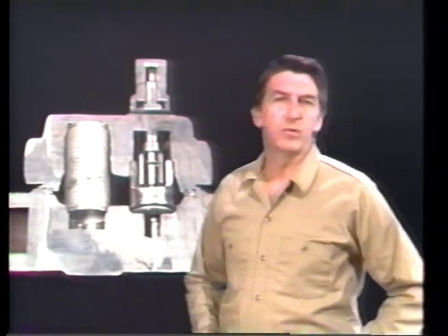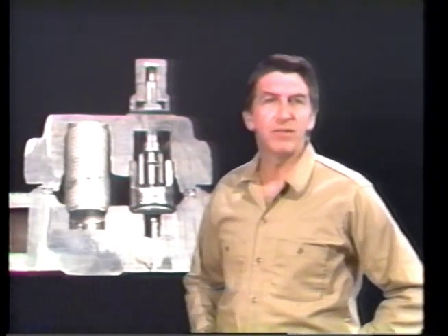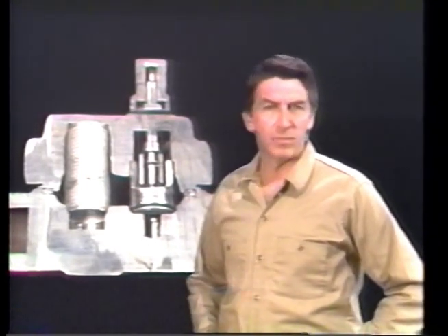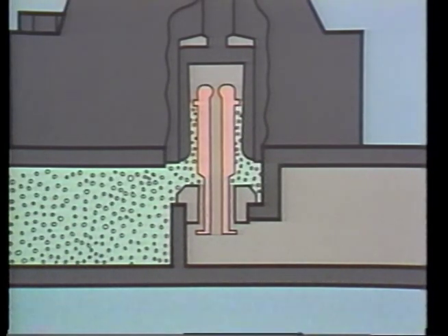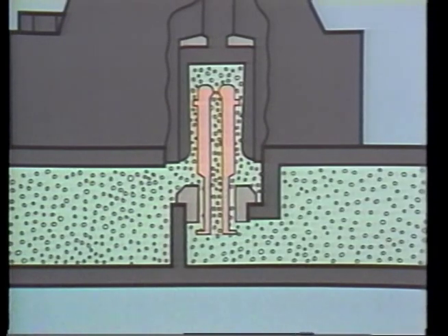And piston traps, as is true of most thermodynamic traps, have excellent air removal capabilities. If air is present at the trap inlet, the air will simply lift the piston and be discharged through the trap outlet and through the control orifice. Air will continue to be discharged until steam or hot condensate reaches the trap.